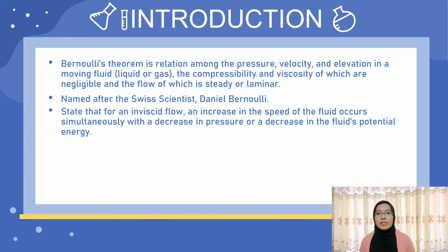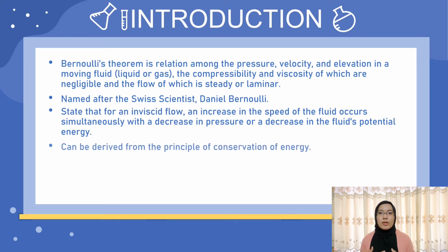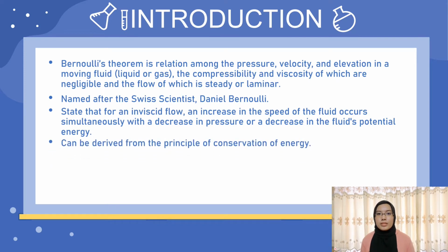Bernoulli's principle states that for an inviscid flow, an increase in the speed of the fluid occurs simultaneously with a decrease in pressure or a decrease in the fluid's potential energy. Bernoulli's principle can be derived from the principle of conservation of energy. This states that the sum of all forms of energy in a fluid along a streamline is the same at all points on that streamline in a steady flow. This requires that the sum of kinetic energy, potential energy, and internal energy remains constant.